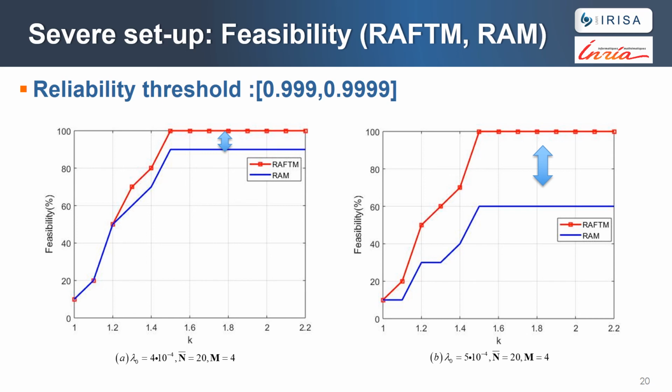The ability of IM to always find a frequency to meet a reliability requirement decreases, especially for tasks with high reliability requirements, since with lambda 0 increasing, the reliability decreases at the same frequency. Our approach is still able to meet these high reliability requirements by duplicating tasks and assigning a high frequency.